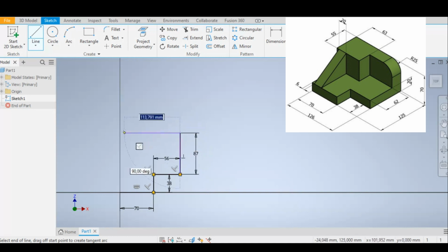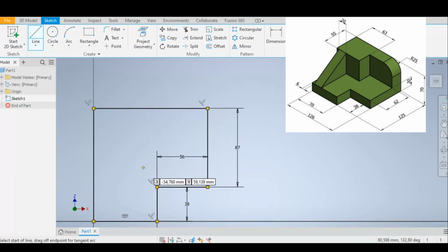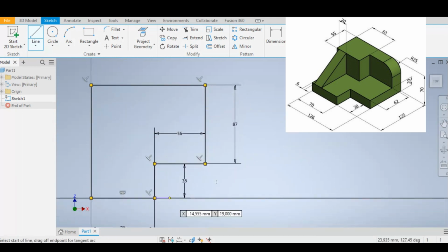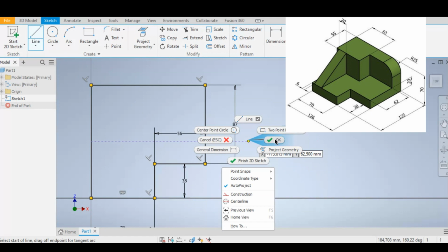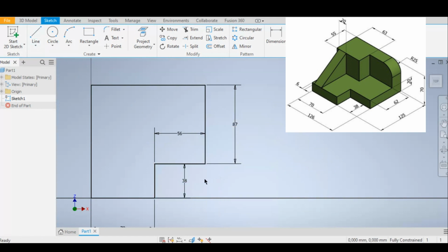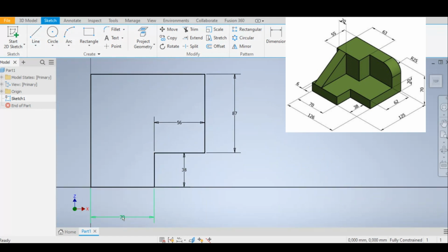So from here, just going to head back to this line and complete our base for this drawing. And if you zoom in, you can see we've got all of these lines drawn up. So to end your line section here, I'm simply going to right click and press OK, and you can then end this section. So from this, you can see we've got a couple of dimensions here.